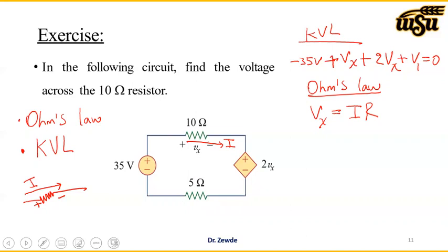Now in this specific case, the resistance is given. We know the resistance, right? So the resistance is 10 ohm. So I'll say R is 10. This will give me 10I. What about the second one? In the second resistor, of course, the current is going this way. I said this is plus and this is minus, and we denote that the voltage is V1.